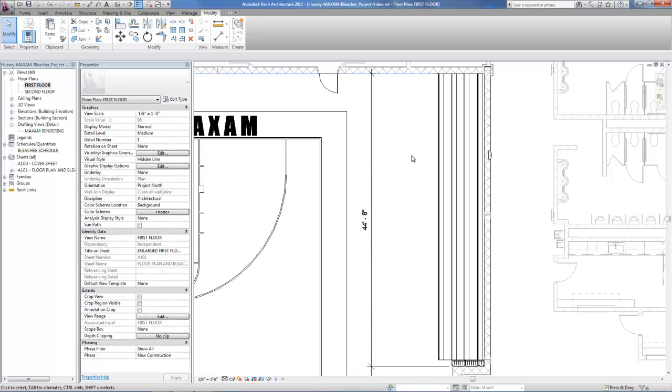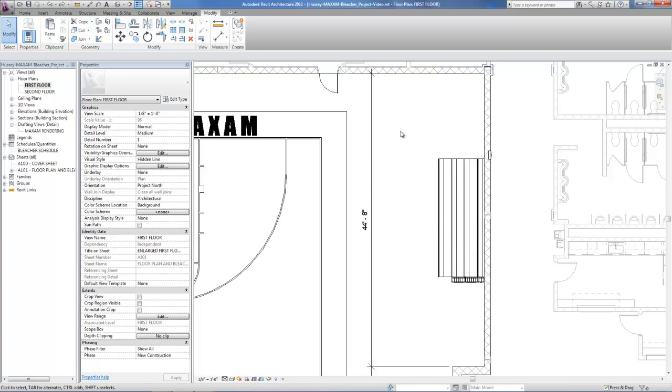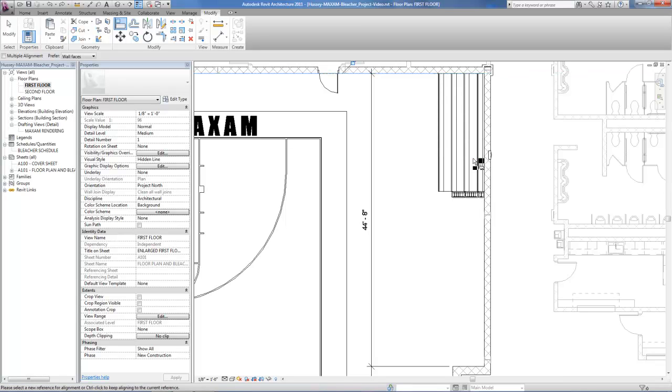That would offer a very schematic option for placing a bleacher layout in a gymnasium, but we've actually given him a little bit more flexibility than that to configure the bleachers more along the lines of what he'll be looking for. I'm going to undo the last two steps to show you what I mean. Again, we're going to do the Align tool, but we're not going to move it down, we're going to move it up to put it in this corner. So we're going to pick that wall, and then instead of clicking to stretch it, if the architect clicks the Tab button and then picks, the entire bleacher bank will move instead of stretching, just to give him a little bit more flexibility.